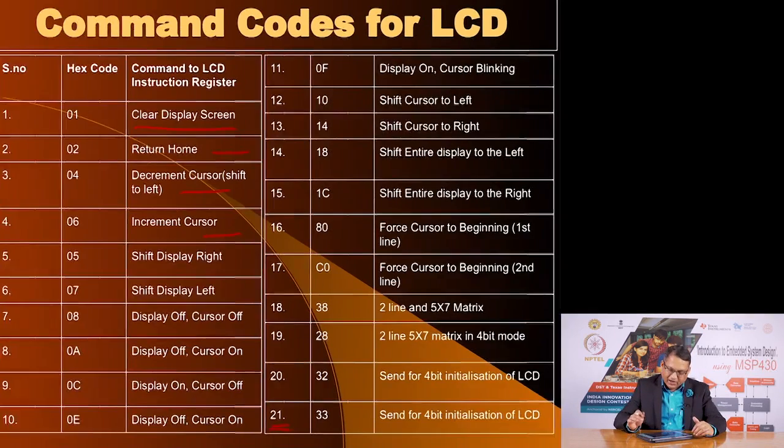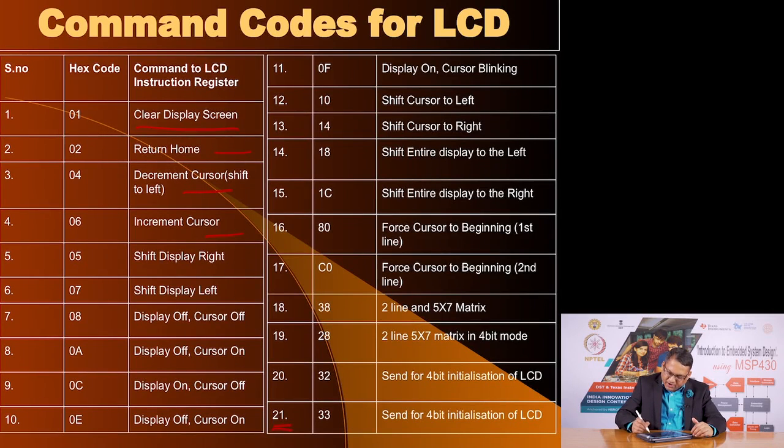In fact, as you see here, these two commands allow you to tell the LCD that no, we do not have 8 pins to communicate with you and we are going to send information on 4 bits also. So, you have to send these commands, and we will see briefly how you send these commands. So, you have an 8-bit mode and a 4-bit mode.